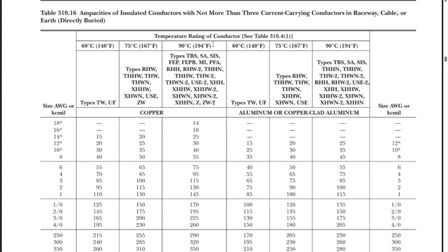So, in other words, now going back to those sections that we read, the termination points have to match, or rather I should say, the wires have to match the termination points and not be less than the rating of the termination point. All right? For example, if the termination point says it has a temperature rating, and they will all only have one of these 3.